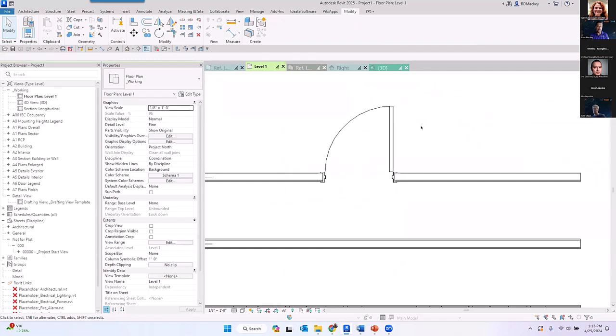So what you'll see, I'll do that again real quick, is if I come in here and hit the align command, you'll see that it is showing me what family it is from, and what the reference is after the colons. If this was a work shared project, you'd also see the work set, but then it's also telling me what name I gave. So I'm always going to go through and name every single reference plane because it assists me also inside of that project.